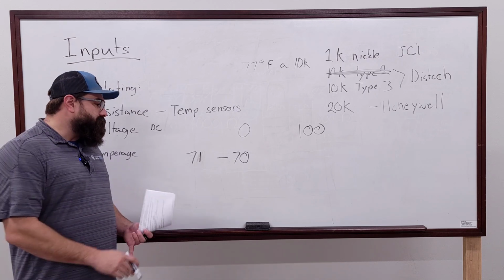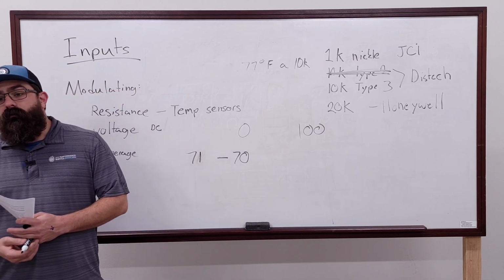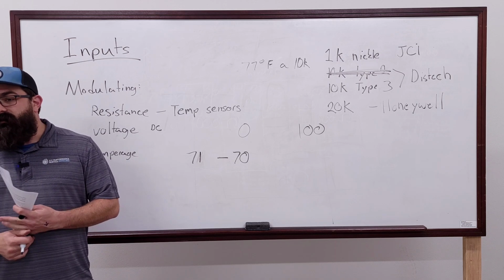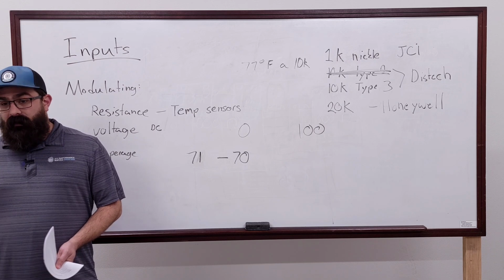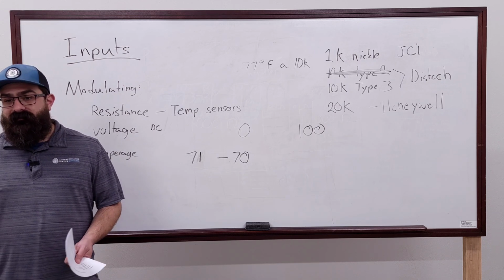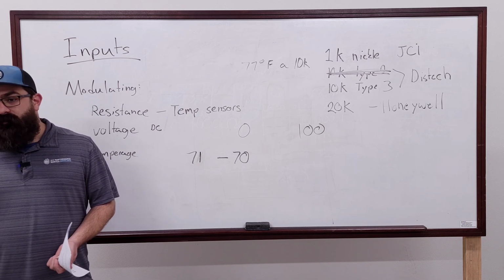So, I don't know. You have to put in a correcting factor if you were to say run. Well, we would just calibrate it at that point, right? There's not like a correcting factor. They give me an offset in the controller. Like when I go to that input, I can offset it based on whatever facet it is. If it's temperature, I can offset it by so many degrees. If it's pressure, I can offset it by so many PSI.